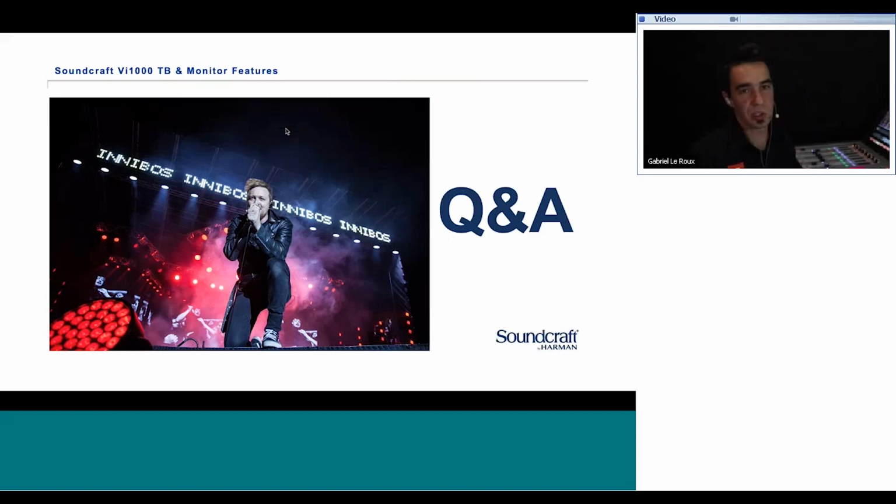So I guess you can trim it up. Something that I've also found, and I forgot to mention it, and this is probably one of the biggest tricks when it comes to mixing monitors, is that I always calibrate all my outputs. So when I'm hitting, for instance, 0 on my metering, I would also hit the same level on the metering on the in-ear transmitter.